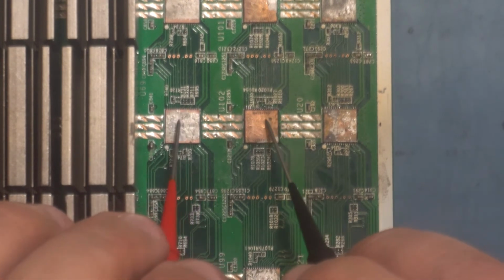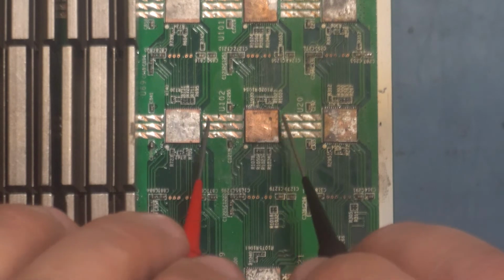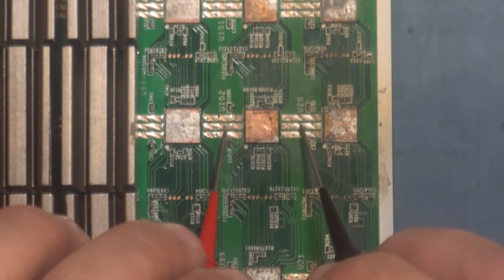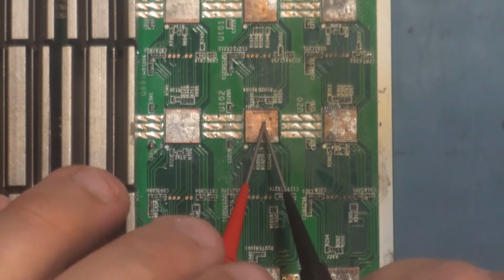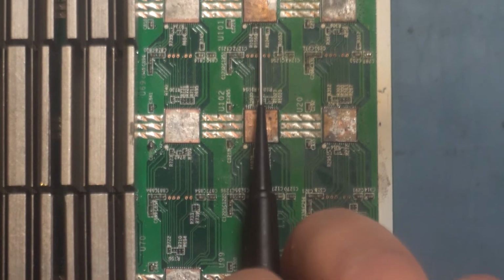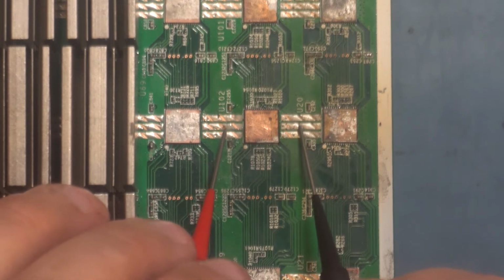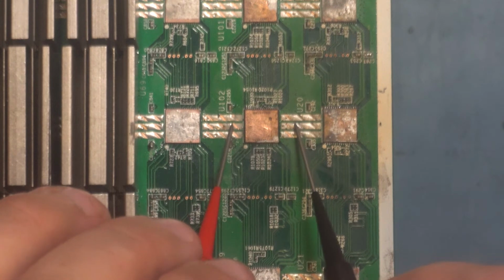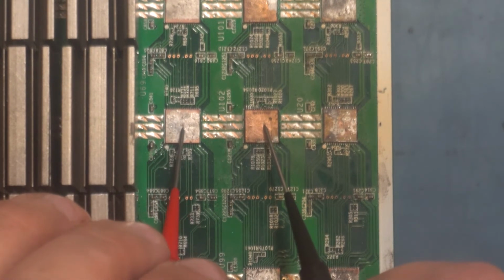So if I don't have a voltage domain value, or if it's zero basically, then that means I'm gonna have the same thing measuring like this, and it means ultimately that something in that second domain is not happy. So any of the 5 chips in this second domain could be shorted internally, which means I would not have any voltage difference when I measure it like that, right? And so this is just something to keep in mind.